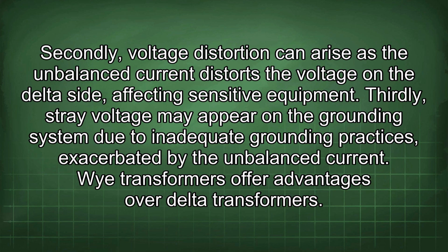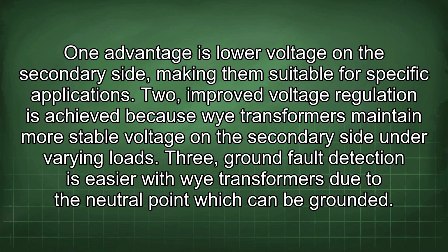Y transformers offer advantages over delta transformers. One advantage is lower voltage on the secondary side, making them suitable for specific applications. 2. Improved voltage regulation is achieved because Y transformers maintain more stable voltage on the secondary side under varying loads. 3. Ground fault detection is easier with Y transformers due to the neutral point which can be grounded.